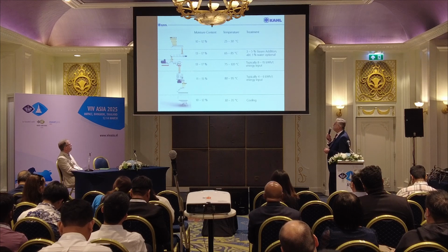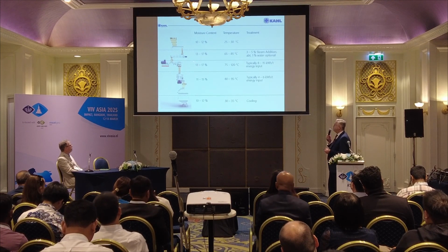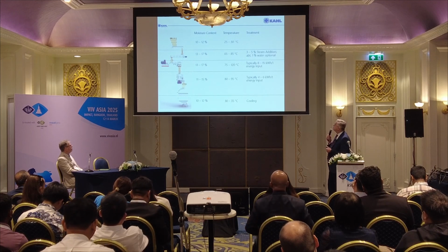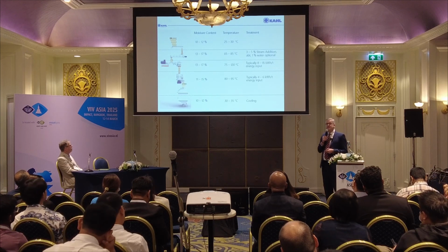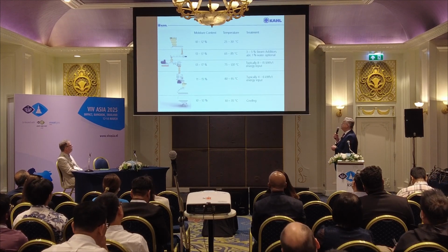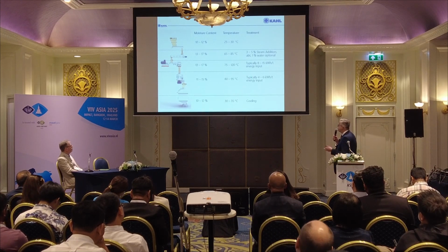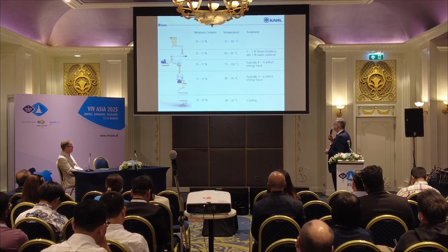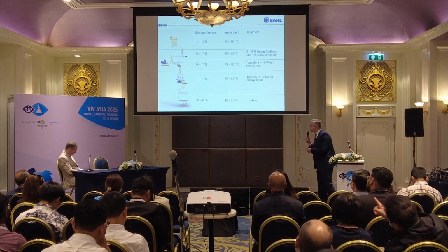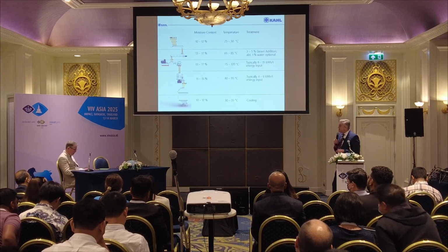What we see after the expander is a flash-off effect. We lose about 2% of moisture at the outlet. That's why we can also add 1% here. The pellet mill will not slip because it doesn't need to compress, it's only shaping. The material is very easy. Starch gelatinization has happened, so it's very easy to shape a very good pellet. Then we go to the cooler, as usual. The cooling ensures that the moisture goes to the desired levels. So that's the thermodynamics of a line.